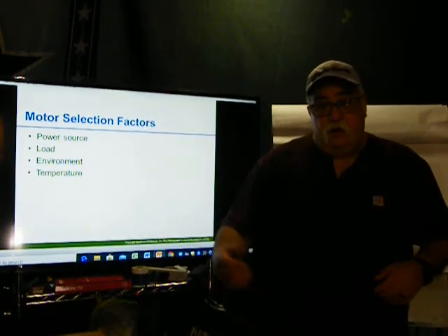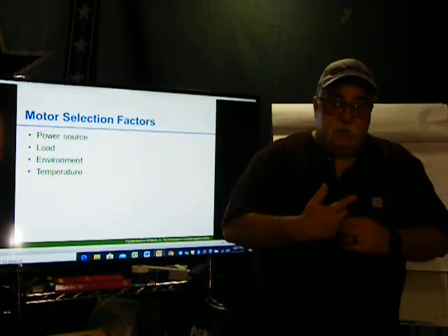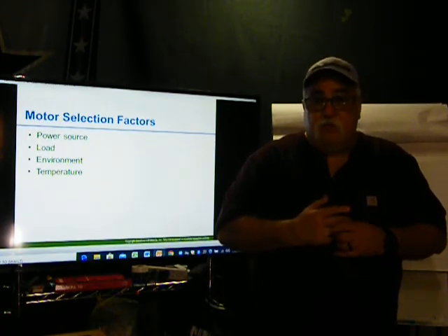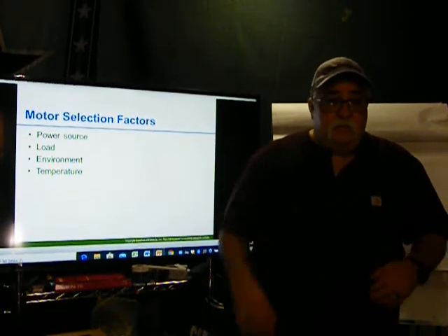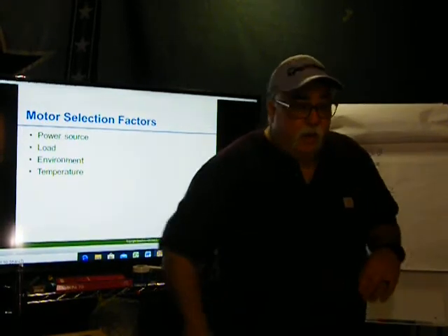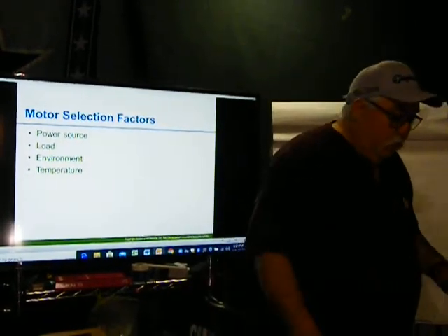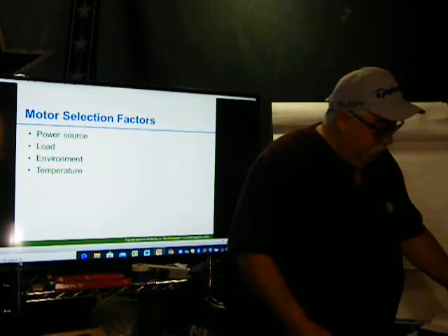So we changed the wiring, we changed the motors to ones rated for a higher ambient temperature, and then we put in some fans to try to control the heat, an exhaust fan to exhaust the heat, and we put in some vents to supply cool air. But that wasn't added till after we spent 4 weeks in there sweating our butts off in 130 degrees.